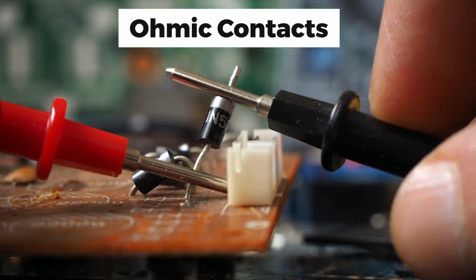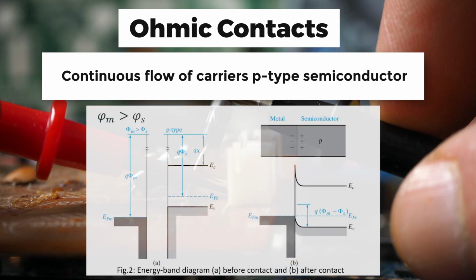Let's take the case of a p-type semiconductor. That is, we want to make an ohmic contact for a p-type semiconductor. In this case, the work function of the metal, represented as phi m, should be greater than the work function of the semiconductor, represented as phi s. Similarly, as we have discussed, the case of phi m greater than phi s for a p-type semiconductor results in easy hole flow across the junction in figure 2a.